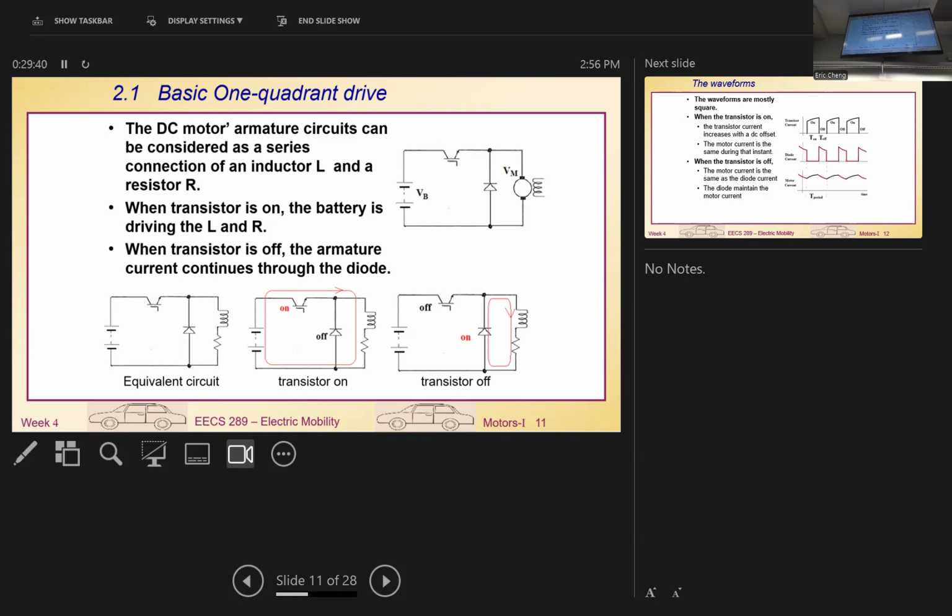So that's first quadrant control. We're able to control the motor's forward motion. Here, we have not considered any power regeneration. What is power regeneration? The current returns back to the battery source. But this current, without doing anything, is only looping here.